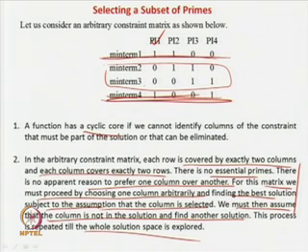To cover minterms 2 and 3, the choices are you take P3 and both will be covered, or you take P1, P2 and P4. So, the new solution space. What we do here is arbitrarily take one column and then repeat the problem. Here it is a small one, so you will obviously take P3 because it will cover both the terms, otherwise you have to take 2 terms.